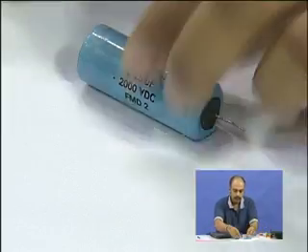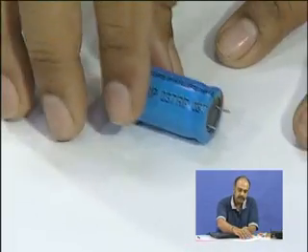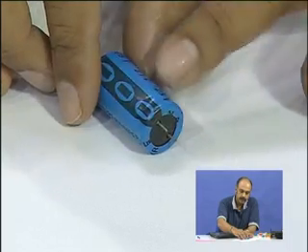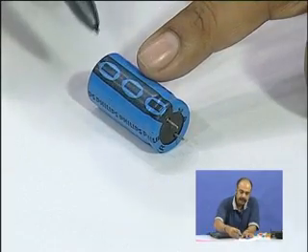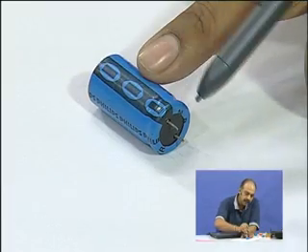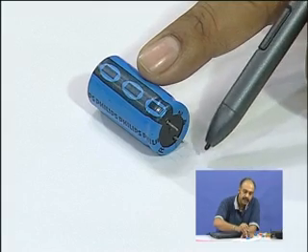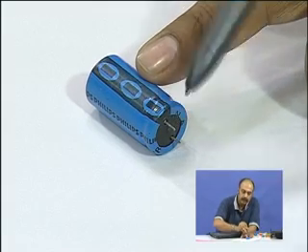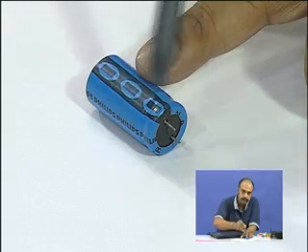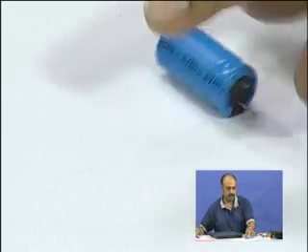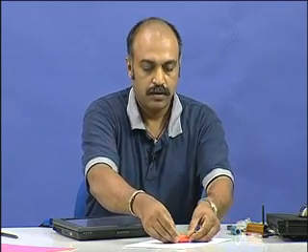I will also show you another capacitor. This is an electrolytic capacitor, polarized, of similar size. You see here the two terminals and see here the minus marking, which means the terminal which is closest to the minus marking is negative and the other terminal is positive. So, that other terminal should be more positive than this terminal. So, always look for a polarizing mark on the capacitor which says that that terminal should be either more positive or less positive than the other terminal. Let me show you something bigger. Do you see this capacitor?